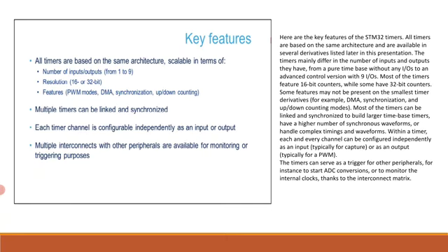Most of the timers can be linked and synchronized to build larger time bases, have a higher number of synchronous waveforms or handle complex timings and waveforms. Within a timer, each and every channel can be configured independently as an input, typically for capture, or as an output, typically for a PWM, pulse width modulation. The timers can serve as trigger for other peripherals, for instance to start ADC conversions or to monitor the internal clocks thanks to the interconnect matrix.